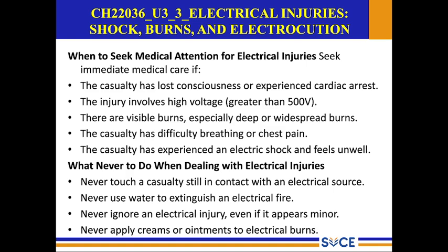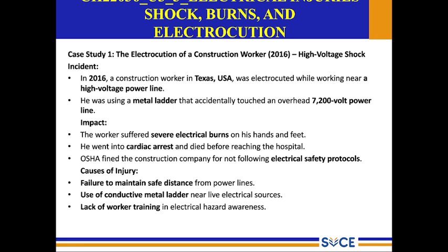What never to do when dealing with electrical injuries. Never touch the casualty when the casualty is still in contact with the electrical source. Never use water to extinguish any electric fire. Never ignore an electrical injury, even if it appears to be minor. Never apply creams or ointments to electrical burns.